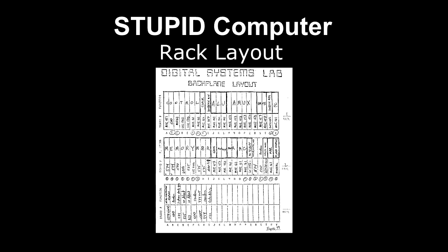We'll go jumping back up to the top. Look in D and E on the top rail there. LSI 1702, those are the ROMs, which were EPROMs, which hold the microcode. So pretty much A through I there is the microcontroller. And the rest of it is the guts of the actual computer. Okay, so this gives you an idea of how many chips were involved. If it's 1 chip per slot, then, what have we got? This is like 22 per, so it's 50 some odd chips, or thereabouts.